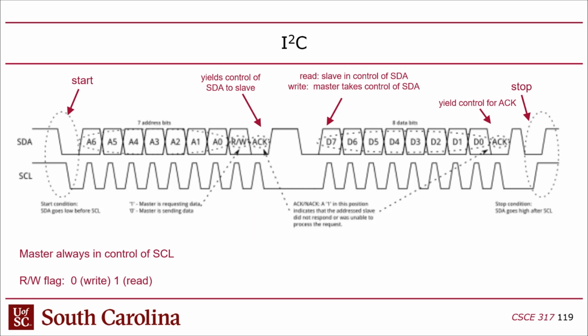The other thing you should keep in mind about I2C is it's usually 8 bits per word, but there are 9 bits in the first and second half because the acknowledgement adds a 9th bit. So the total number of bits here is 18: 9 for the header, 9 for the data. I think you should be okay as long as you understand that: it's level sensitive, there's a start and stop, and it's 9 bits and 9 bits.